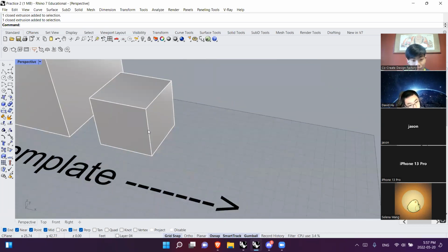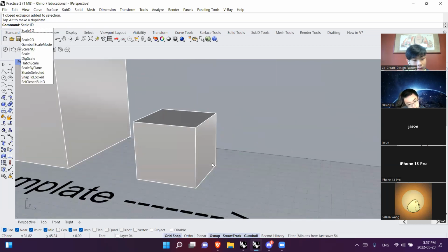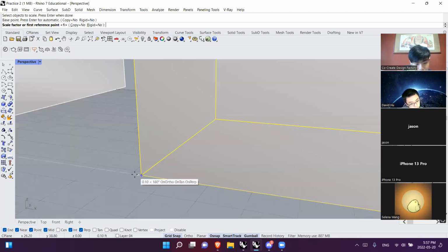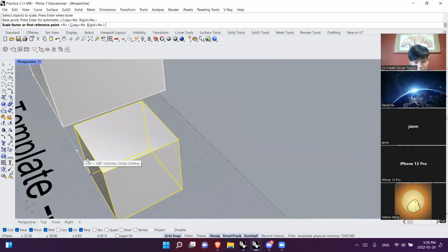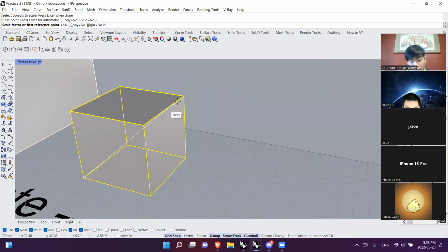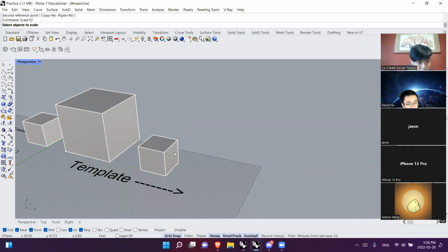However, on the other hand, there is another command that you can use, which is called scale 1D. Don't worry about scale 2D for now. With scale 1D, when you enter the command, you select the object to scale. You also have a base point. Again, this is our base point, and it's going to land on the same axis. And now you have to select your other reference point. Let's say we do the same. Oh, actually, that's not a good reference point. Let's do that command again.